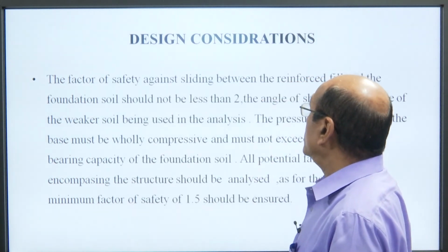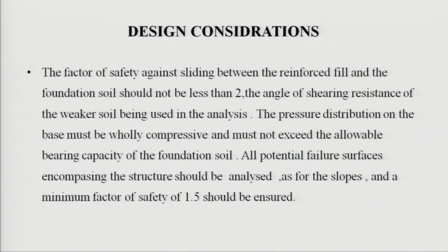Now, the factor of safety against sliding between the reinforced fill and the foundation soil should not be less than 2, the angle of shearing resistance of the weaker soil being used in analysis.